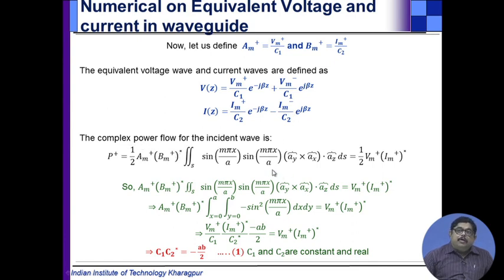Now, enforce the power equivalence. So, first find out from the field ones with these definitions what is the incident power. All the steps are done for you, Poynting vector, then integration over the guide. S means the transverse cross section of the guide, that means for a rectangular waveguide x is from 0 to a, y goes from 0 to b.